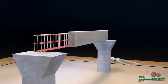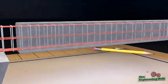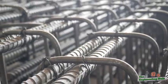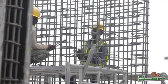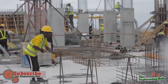But if longitudinal rebar takes tension on the bottom and concrete takes compression on the top, then what is the purpose of the stirrups? Many people in construction believe that the stirrups are only there to hold the longitudinal reinforcement in place. Though that is true, it is not the main reason for their use.